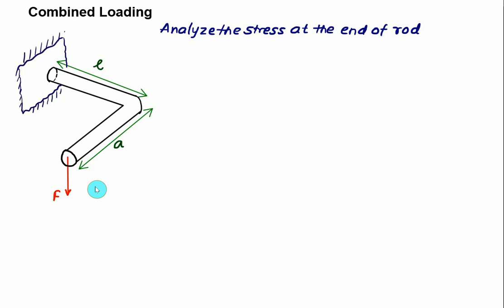There are an infinite number of stress vectors at any point inside a member subjected to combined loads, as an infinite number of planes can pass through the point. Each stress vector is characterized by the surrounding plane on which it is acting. And the state of stress at a point is the totality of all the stress vectors acting on it.